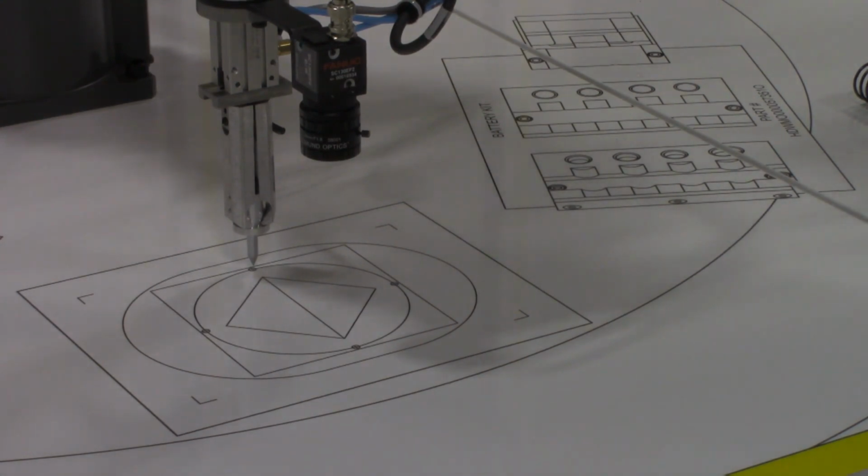The only other thing I'd like to do is to have it park itself in between each of these moves. So I'm going to add some position registers inside of there. Basically drive the robot home, go home, make the outer square, go home, come back, make that diamond shape in the middle using linear, go home, and then make the circle. So we can edit these programs inside of the teach pendant.